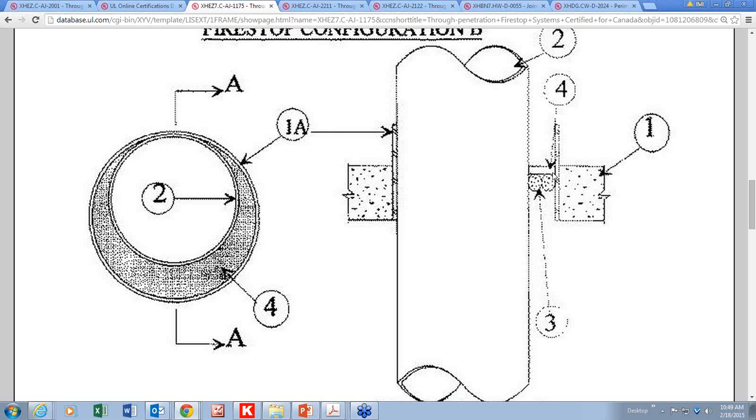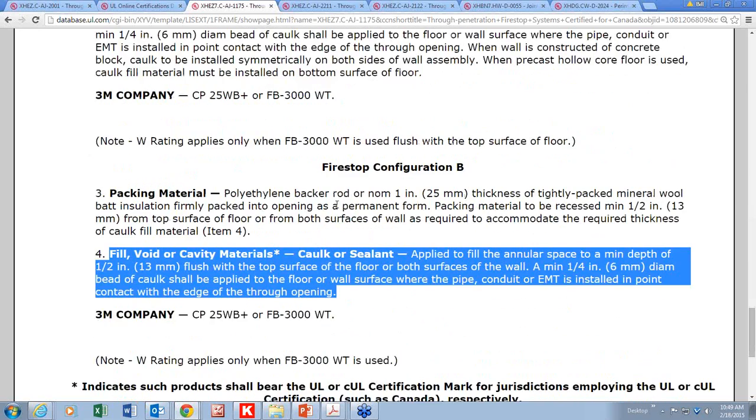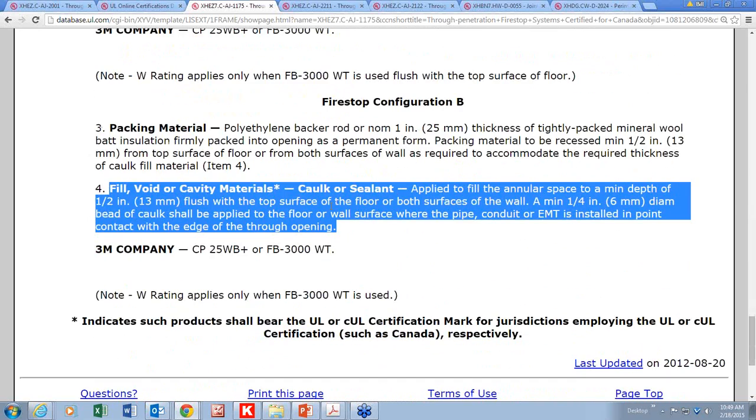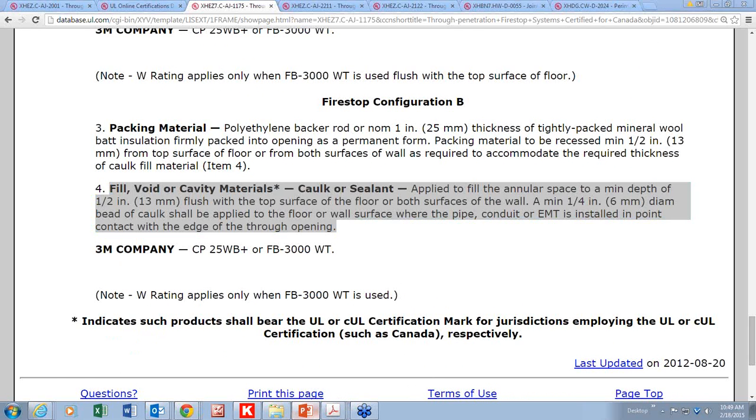And you get that information and the calculation method from the manufacturer of that Firestop sealant to verify that whatever they put in at the initial set was the accurate thickness. In Firestop sealants, the thickness is specified, but if you notice, the thickness doesn't say whether it's wet or dry. Huge question, huge thing to keep an eye on. Back to the presentation.